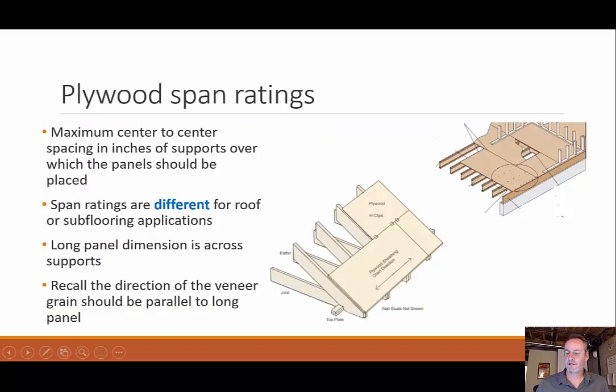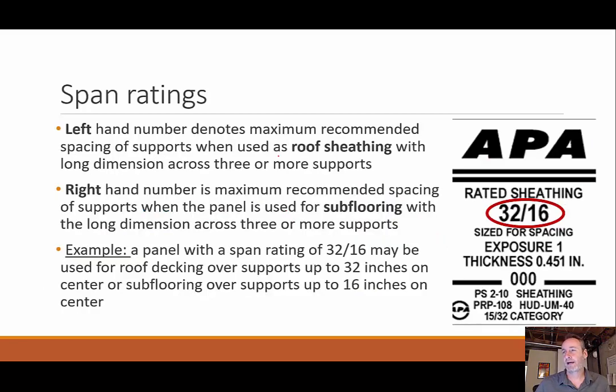So as I said earlier, we're going to be running our plywood in this long direction, and the question would be, how far can the plywood span between any adjacent supports? And of course, this would be different for roof or subflooring because you have different loading scenarios, right? Typically, you have a higher total load. We talked about dead load and live load and all your various loads in your flooring than you would on your roof. And many times the allowable span will be rated right on the plywood.